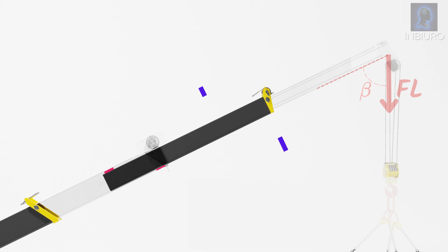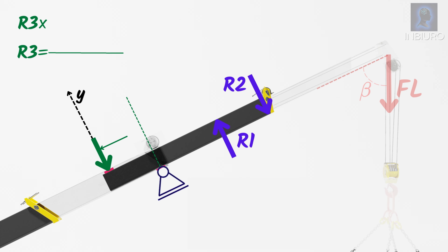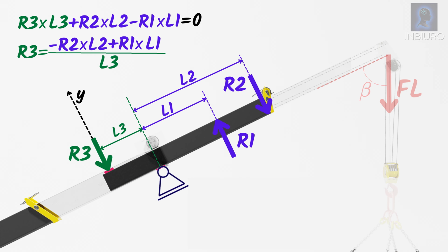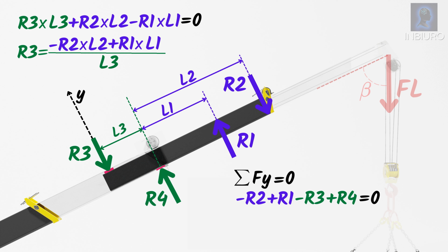Note that the sliding pad's forces act in the opposite directions compared to the other boom section. Unlike the very end section, on every next section right end, we have two forces of sliding pads contact. Again, we calculate top end pad load R3 from balance of bending moments, and bottom pad load R4 from balance of all forces projected on direction Y, perpendicular to the boom.